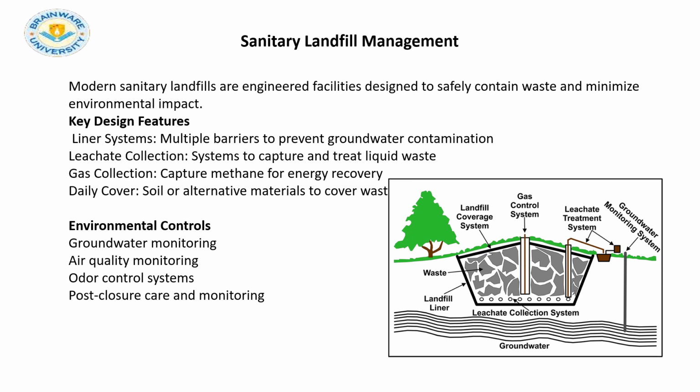The key design considerations are liner systems, which are applied in order to prevent the contamination of groundwater. Then there is leachate collection. Leachate is the contaminated liquid which comes out from the solid waste, so we need to capture the leachate and treat the liquid waste.